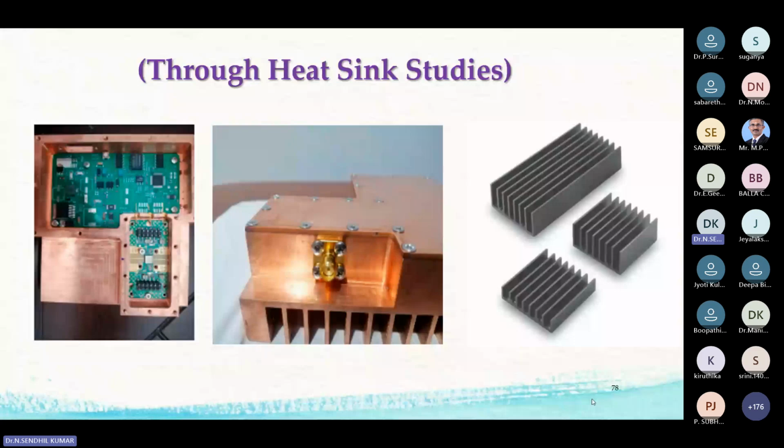So here you can see the heat sinks. You will place the heat sinks at the backside of the power electronic components. For this small area you can attach a heat sink with a number of fins. You have to calculate how much heat is available, and accordingly plan how many fins to use and what the spacing of the fins is. You can design all those things. This is the heat sink study.